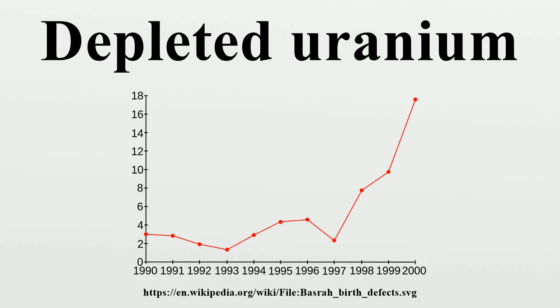The storage of DUF6 presents environmental, health, and safety risks because of its chemical instability. When UF6 is exposed to water vapor in the air, it reacts with the moisture to produce UO2F2, a solid, and HF, a gas, both of which are highly soluble and toxic. The uranyl fluoride solid acts to plug the leak, limiting further escape of depleted UF6. Release of the hydrogen fluoride gas to the atmosphere is also slowed by the plug formation. Storage cylinders are regularly inspected for signs of corrosion and leaks, and are repainted and repaired as necessary.